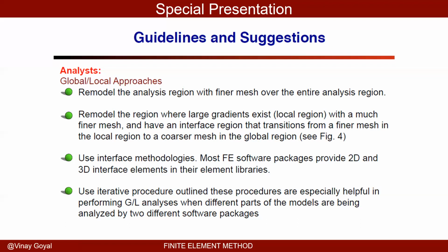It is singular to the order of the rigid body motions you have: 6 in 3 dimensions, and 3 in 2 dimensions. So there is no way you can get an eigenvalue answer if you look for the eigenvalues of K inverse times M. That's what he's trying to do.